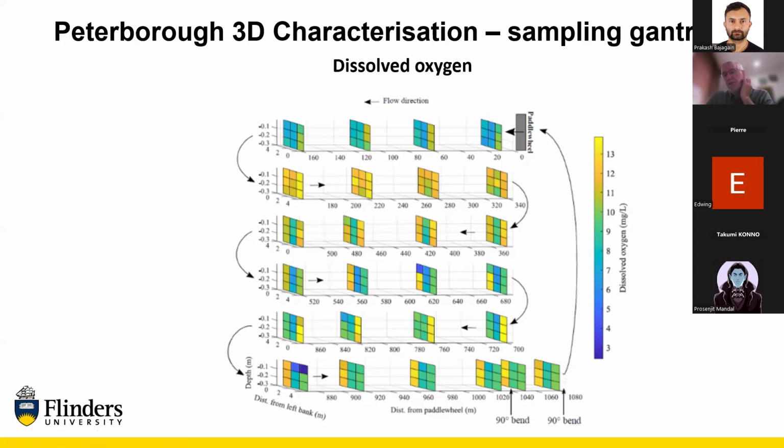I'm really just talking about it because it's practical microbiology. How do you do measurements on these very large systems, and how can you try to control for changes? How can you at least measure changes? And we know the reason we couldn't get the compensation as good as we thought we could was because this fixed probe here had a lot of biofouling.